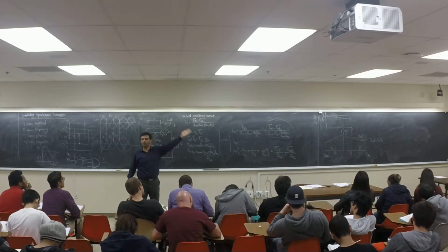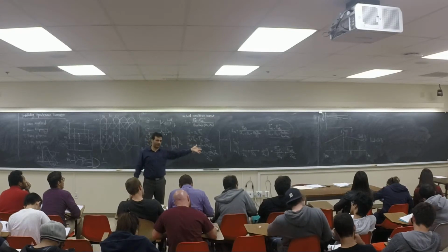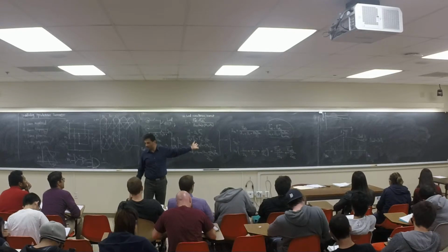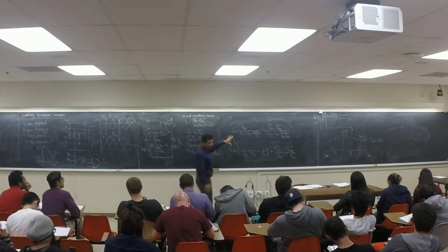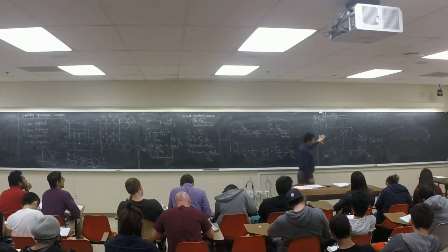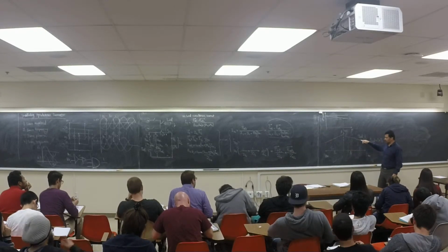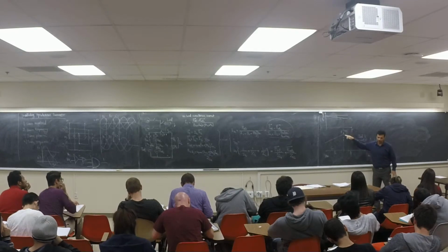If you increase 10 kilowatts, 7 kilowatts is going to come from the right side, right? 3 kilowatts is going to come from the left side, right? So this is a very, very common characteristic for generators. They call it group control. They use a group control because there is a group here. You know, they can change the frequency based on this one.